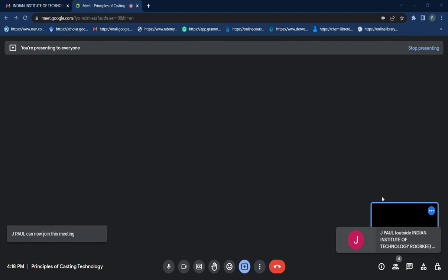Okay, so it will be around 894 centimeter cube. Okay, so now after this we will focus on this appendage or bar. After doing this part, we will focus on this part. Firstly we assume that there is no bar. From that we found the volume of the riser as 894 centimeter cube. Now we will find the volume of the appendage or this bar.